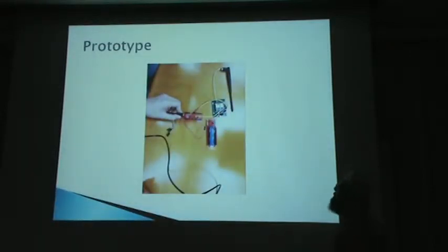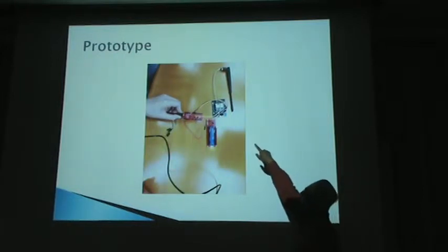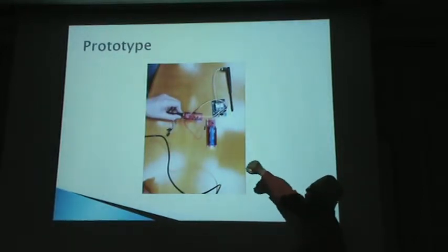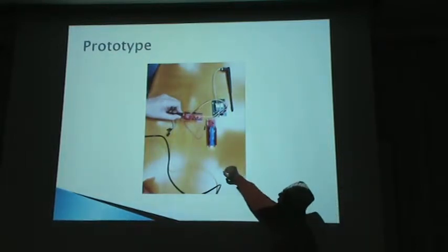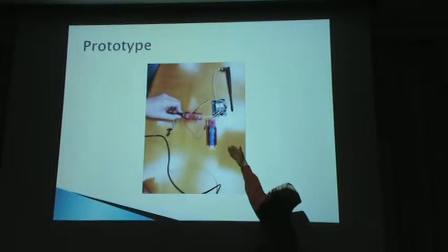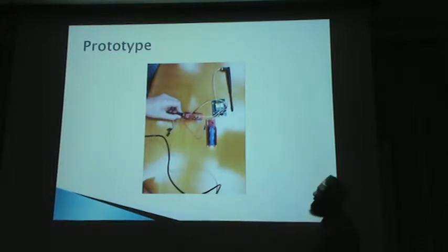That's our first prototype that we successfully managed to do. Here the buzzer is not there and the battery is not there for now because we are just doing the prototype testing. So that's the breakout board, the RFID IC is right in there, the microcontroller is an Arduino Fio V3, and the LCD shows here: sensing tags. So that's a successful test.